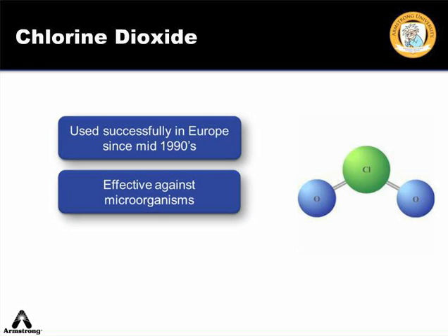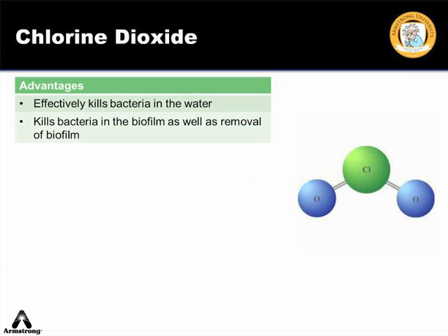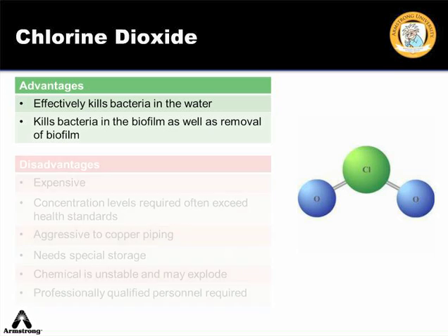Chlorine dioxide is effective against many microorganisms and is more potent than many other disinfection methods over a short contact time. Advantages are it effectively kills bacteria in the water, and early indications show potential of killing bacteria in the biofilm as well as removal of the biofilm.